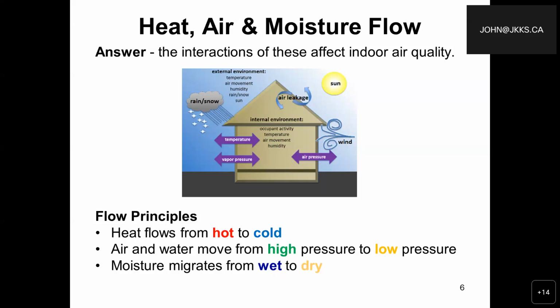Really, I'm not trying to turn you into building science specialists, but I think we need to talk about a few basic science principles that do apply, which are presented on this slide. We often hear that heat rises, and that is true. But often what we don't realize is that when heat rises, it also escapes through those external cracks, crevices, and air leakage points within the building envelope, from a number of different locations. Uncontrolled air leakage through the building envelope is most often the cause of housing performance issues and problems, such as the development of mold.